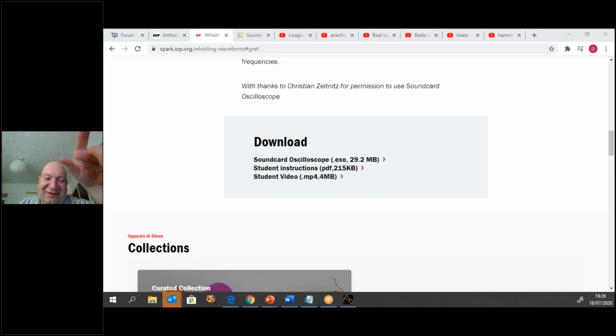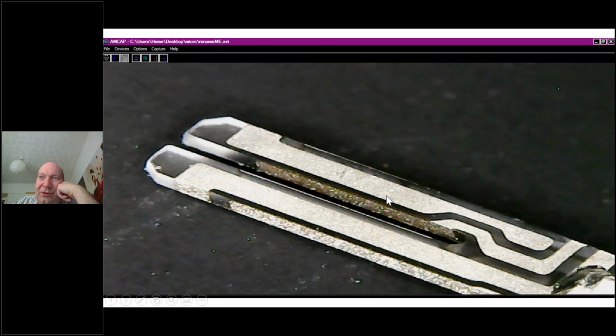So, now let's see what we do in terms of this quartz. This is a piece of quartz that's been cut. This I took out of a watch. When you watch Steve Mould do this, he connects an oscilloscope to the wires and flicks it, and you see the signal it makes. But what I want to get across to you is that this is a real tuning fork. Some watches run on mechanical tuning forks as well, but this is a tuning fork. When it's squeezed, remember, if you squeeze the quartz, it makes a current. So when this thing oscillates the quartz, it makes a p.d. that's changing.